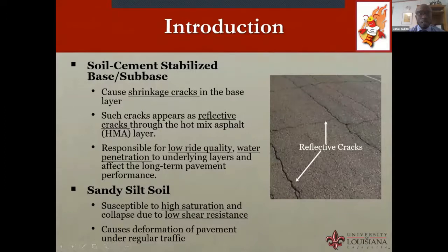As an introduction, I want us to understand that presently the soil cement stabilized base or sub-base layer that we have for our pavement is not sustainable, because we have shrinkage cracks in the base layer as a result of temperature change. We also have cracks that tend to appear as reflective cracks through our pavement layer. Overall, these are responsible for low ride quality and water penetration to the underlying layers, which tend to affect the long-term performance of this pavement.